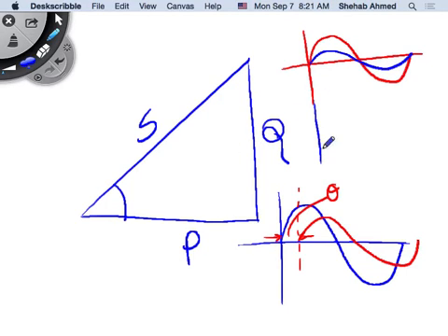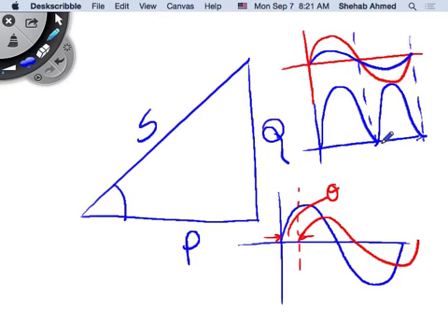And if you multiply them together, what do you get? If you multiply these two waveforms, you get something that looks like this, right? This is p of t. This is V and I multiplied by each other. The two positives will yield a positive, two negatives will also yield a positive, and they are the same magnitude, so it will look like this. So this is the instantaneous value of power.